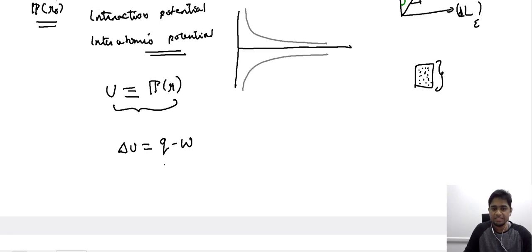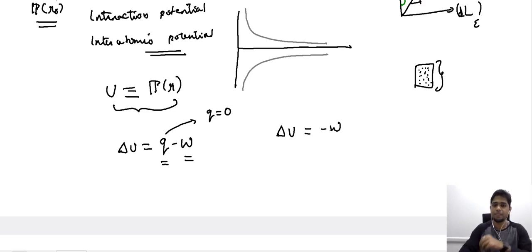Here, this term involves the heat transfer associated with the system, which can be in or out of the system, and W is the work. Now our assumption is that whatever role thermal energy plays in the system is minimal, so this term is rather insignificant. There is no role played by this term here. So ultimately the internal energy change is principally governed by the work that is done on the system.